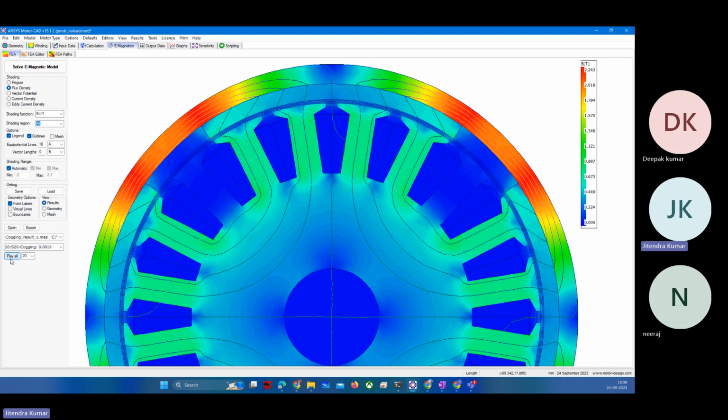To produce DC or uniform torque, both MMF forces, armature and field MMF, should be stationary to each other, right? This concept, I hope. There should be a constant angle between the two fields. So the relative velocity of them should be zero to produce uniform torque, right?